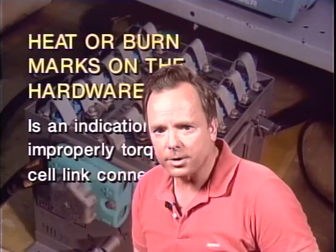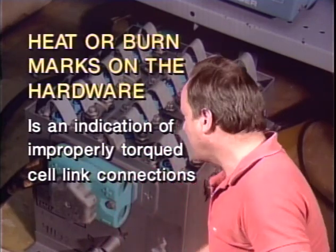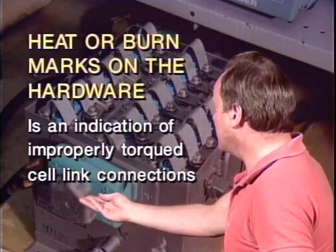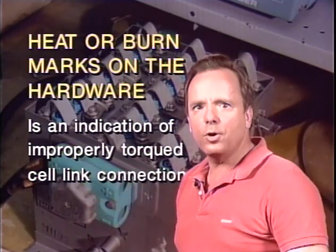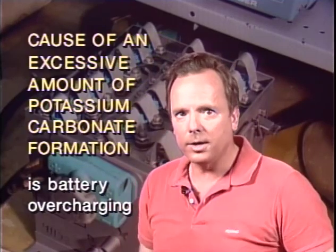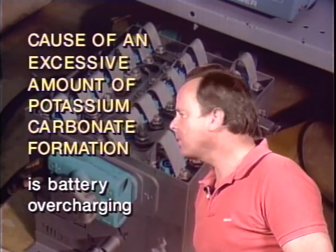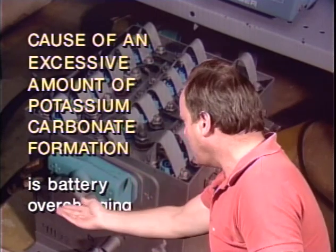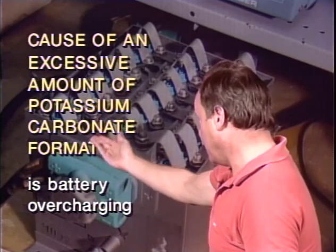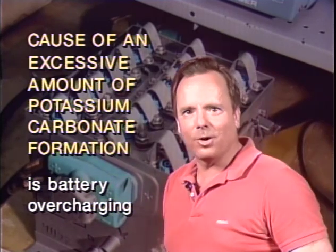Let's assume that you find heat or burn marks on the hardware of a battery. What's that an indication of? Well, it's an indication of improperly torqued cell link connections, and it means you have had some arcing there. What is the most probable cause of an excessive amount of potassium carbonate formation on a battery? The answer is battery overcharging will cause an excessive amount of potassium carbonate formation.